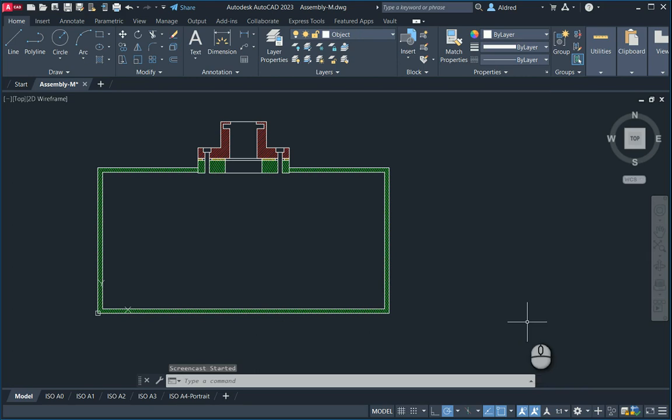In today's video, I'm going to show you how we can use annotative scaling on our dimension objects to create a uniform text height when creating your drawings in your paper space. Normally, we draw up everything 1:1 in model space, we dimension in model space as well, and then we create our different viewports with our different view scales in paper space.